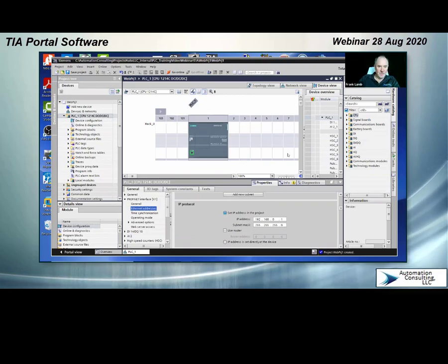Okay, so if I am setting this kind of an IP address, obviously this 255, 255, 255 means that everything else needs to be on the same network, 192, 168, 0, something. So my computer would need to be on this same network. Now it's not in this case. My computer's address is 192, 168, 3, and I believe it's 200. So if I wanted to talk to this processor, I would need to change this mask.